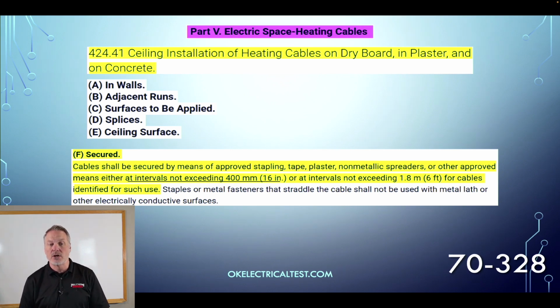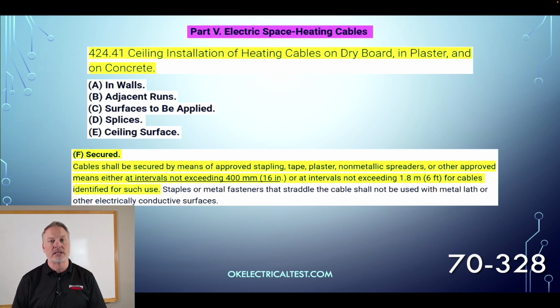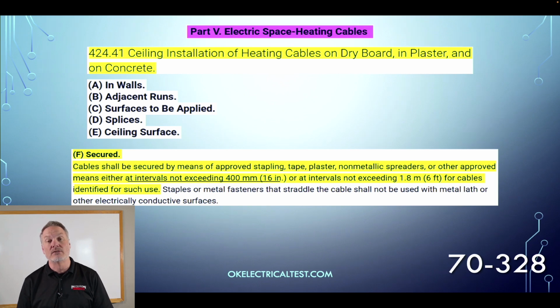Cables shall be secured by means of approved stapling, tape, plaster, non-metallic spreaders, or other approved means at intervals not exceeding 16 inches, or at intervals not exceeding 6 feet for cables identified for such use. So they're just going to ask us, in general, how often does that need to be secured or supported? Every 16 inches, right? They'd have to tell us that these were identified for greater intervals if they wanted us to grab that 6 foot.